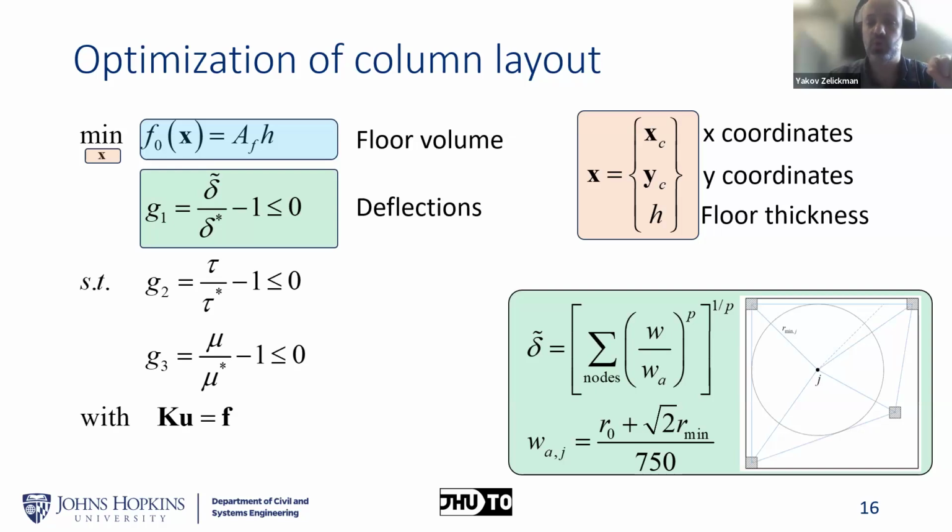Since we don't want to have a constraint for every single point, what we're actually doing is constraining the maximal deflection, or the maximal relative deflection. However, since the max operation is not differentiable, we replace it with a differentiable soft maximum, specifically a p-norm function.